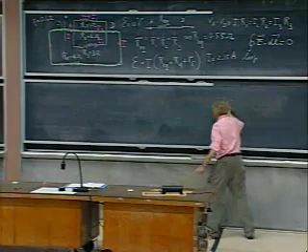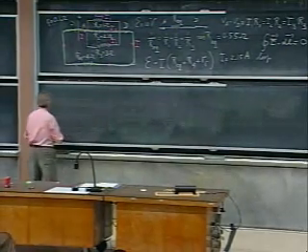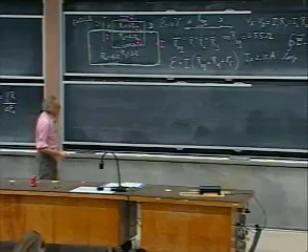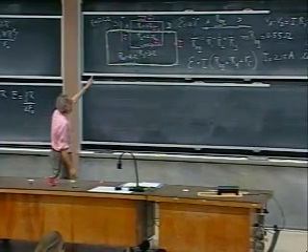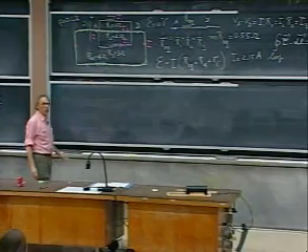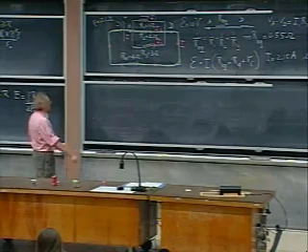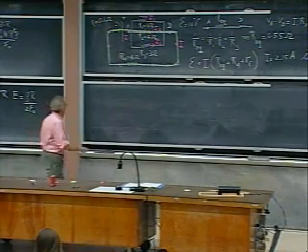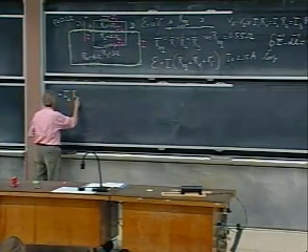So I will stick to my convention for now that if I go down in potential, I will give it a minus sign. If I go up in potential, plus sign. I go first from A to D through R2. The current is I2. The resistance is R2. And I go down in potential. So my first term is minus I2 times R2.